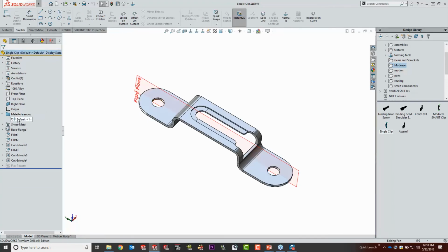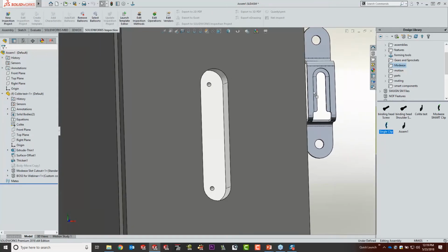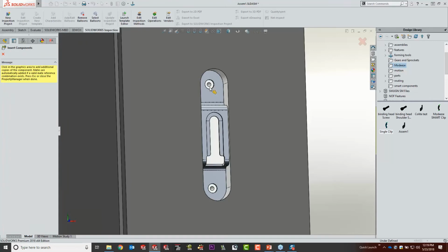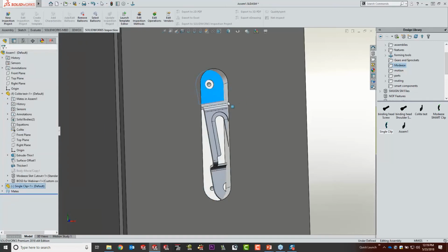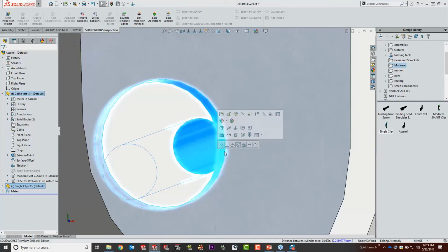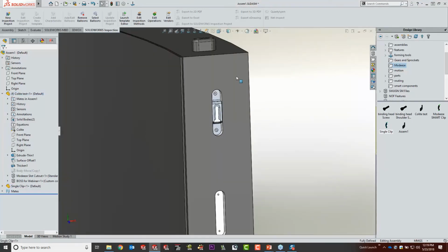And what a mate reference is essentially, a predefined mate that, since I'm not dragging the part by grabbing specific geometry and instead just grabbing it generically off of a library, this is the theoretical drag and drop point. Now what the behavior of that is when I drag it into an assembly and I hover over a hole, it automatically snaps that clip into place. So when I put it there, what I now have is a clip that I can finish up just by simply putting on the final concentric mate, and then that locates that component. But it's a really valuable and flexible tool.